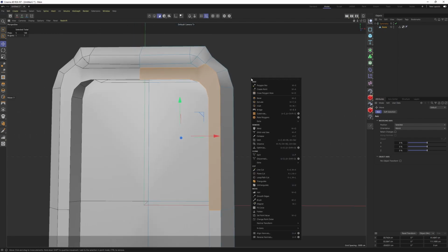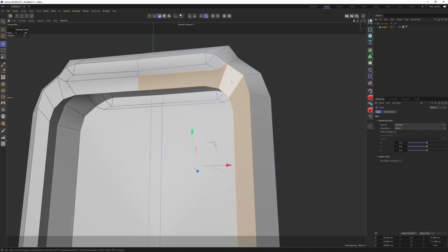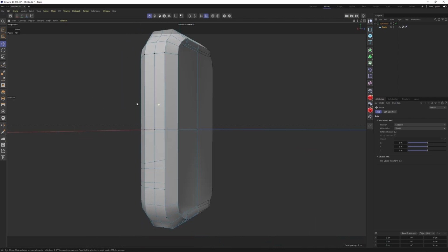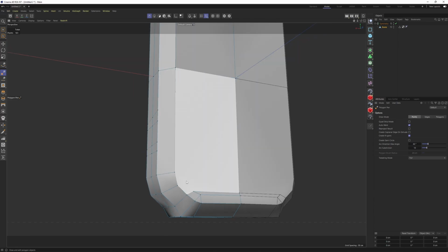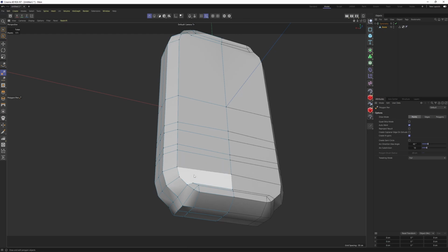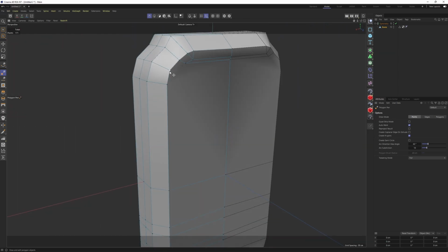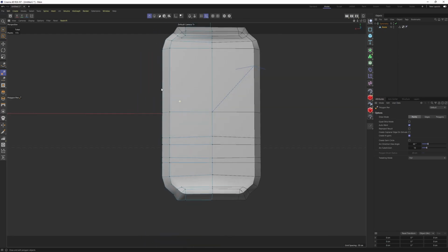Now the top part, right click again, select the polygon islands, n-gons, and remove n-gons. This time, as you can see, it's made a great job by cleaning up the mesh. Now let's try to connect these points like this over here and this one and points.